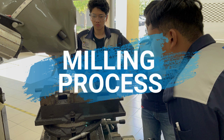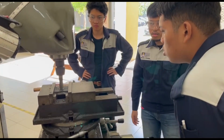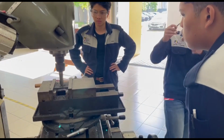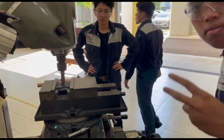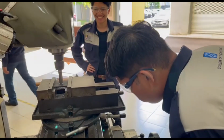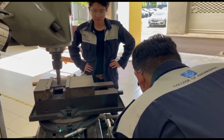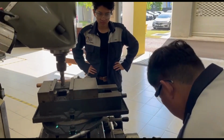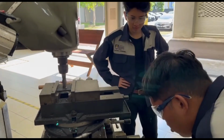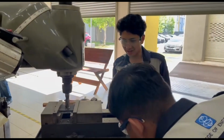After that, we proceed to milling. We mount the steel plates on the milling machine. To find the center of the steel plates, we use a tool to adjust the milling bit. We put the milling bit on the machine and make sure it is tightened properly. The milling bit used is 10 mm in radius.